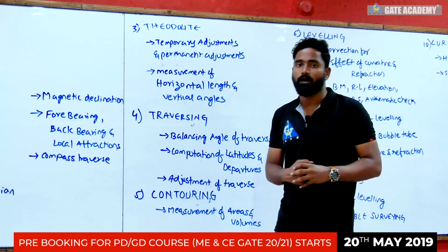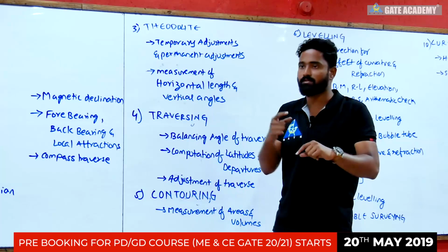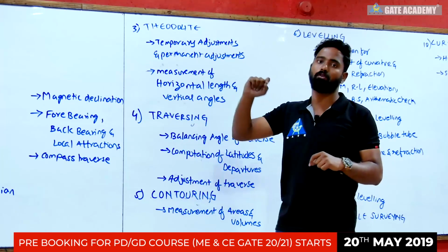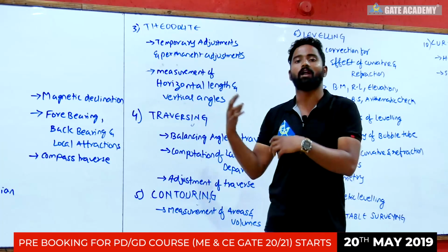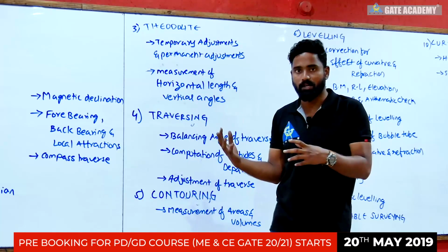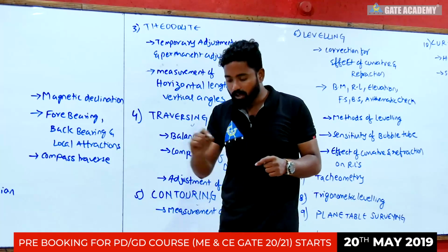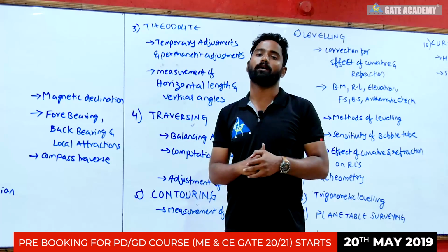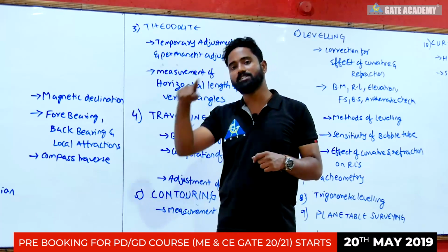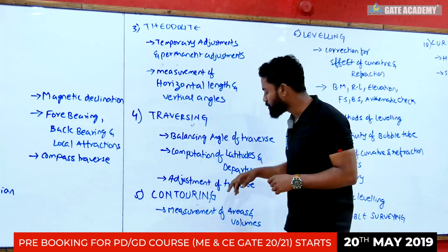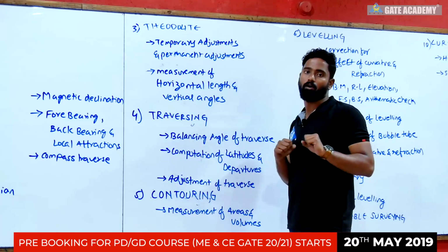And like we say that two contours do not meet, that means one contour is at one elevation, the other contour is at another elevation. So, what are the exceptional cases? Like an overhanging cliff is an exceptional case. It is not meeting exactly in the field, but we show that it is meeting in the map. And how does a valley come and how does a ridge come? All those things will be shown in contouring, and all these things will be discussed in contouring.